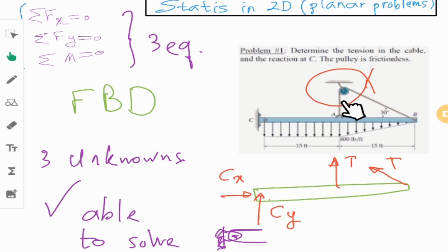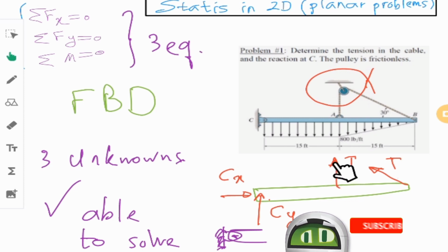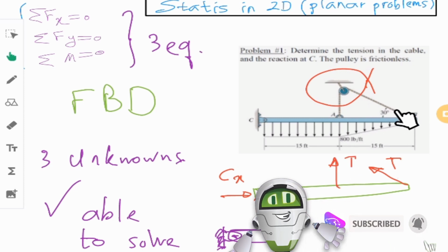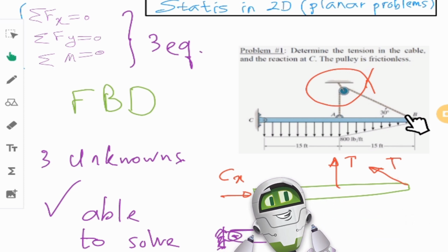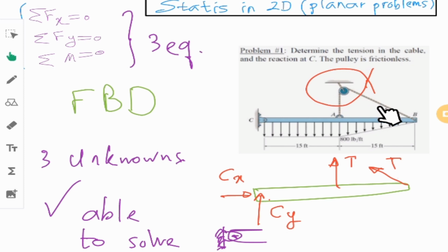Okay, the same story for the cables. The cable can apply only tension. If it goes under compression, it's not static anymore. It starts to get slack and it moves actually, and that's why we put only a tension here. The same story here, and that's why we put only a single tension in direction of the cable and exactly in direction of that cable. That's how I realized to put these guys there and no other unknowns here like M.